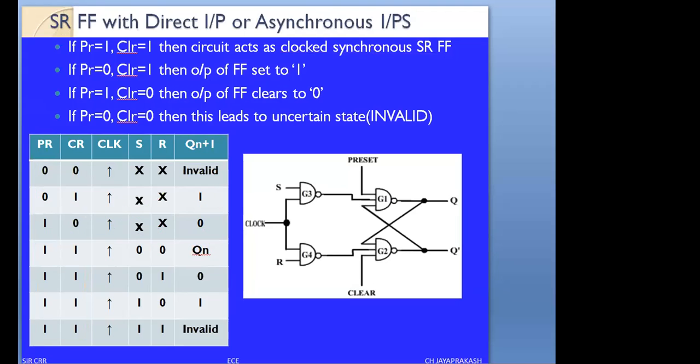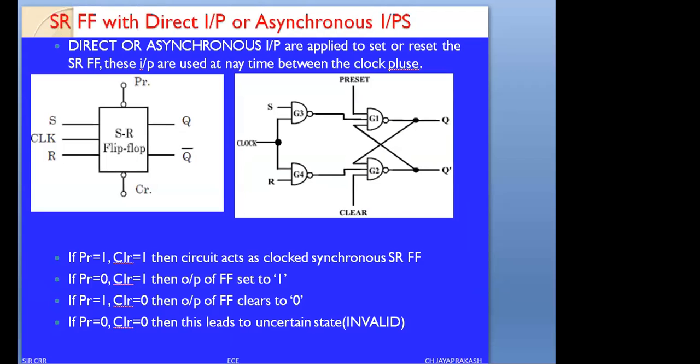See, the SR flip-flop we have studied with a clock signal. When studied with the clock signal, we have called that circuit a synchronous clocked sequential circuit, dependent on the clock. If you add 2 extra pins, preset and clear, we are calling these asynchronous or direct inputs.